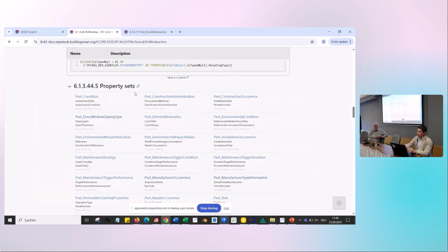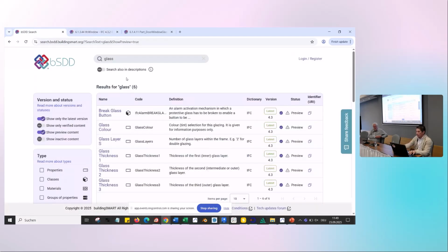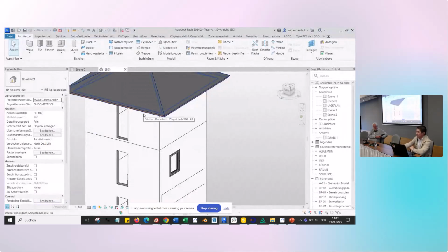You can do the same thing in most likely any BIM authoring tool that implemented the IFC schema. It will actually be integrated in the project, in a BIM authoring tool. But I'm showing that you can also do the same thing through bSDD. Now commonly in Revit, or using Graphisoft Archicad, for example, it implemented an IDS importer. If you created an IDS, you can simply import it. It will be the same way.